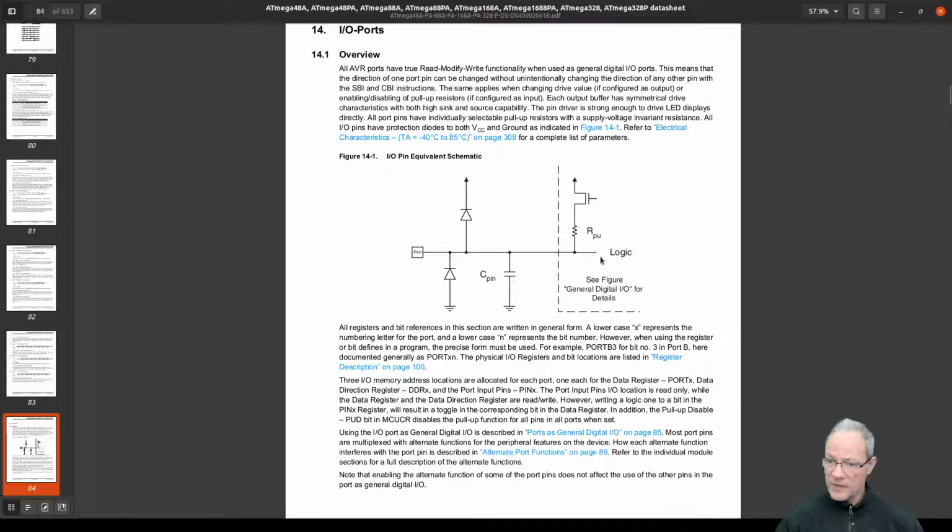If you're reading from that pin, and if nothing is connected to it, then maybe you want it to read as 1. So that's what the pull-up is. You could have a little switch, a button attached to it, and whenever you push that button, then you get the 0 on that pin. But what if it's not pushed? Then you should have a stable 1 on that pin. So that's what this pull-up resistor is for.